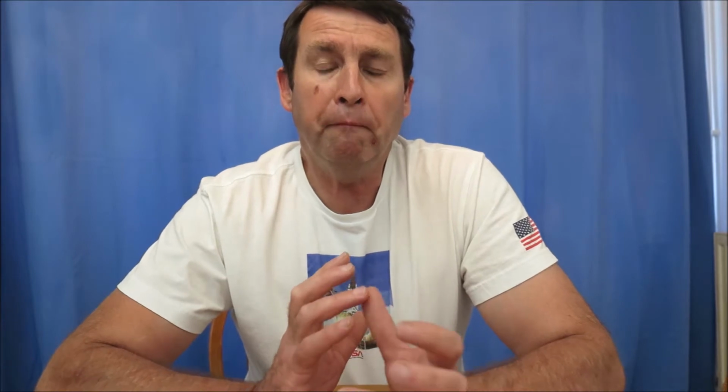And it develops from wound components like motors and transformers where they use coils, and it's the forming of the magnetic field around these components. But of course, as the mains signal rises and diminishes, so does the magnetic field. And when the magnetic fields collapse, then you have a back EMF, which is essentially fighting against the source voltage.